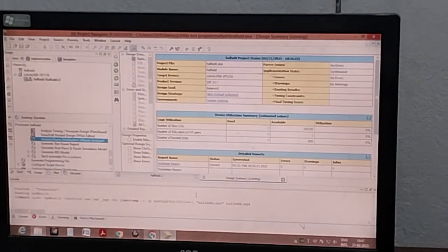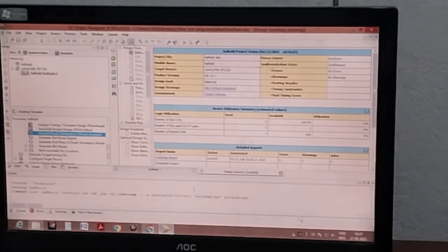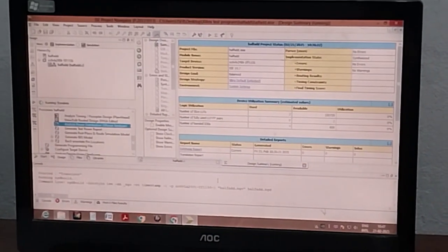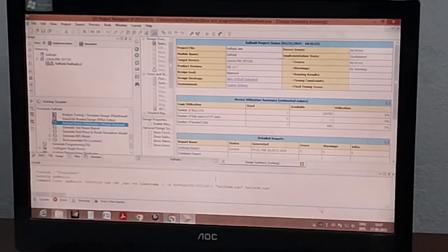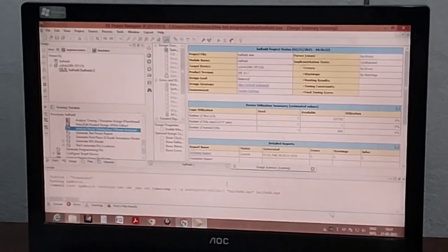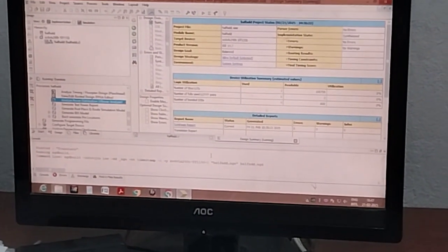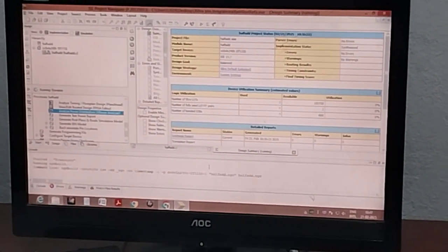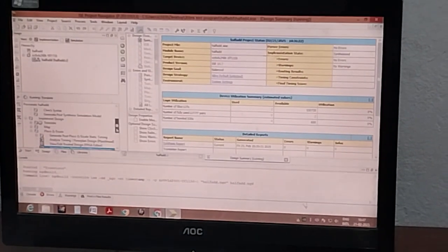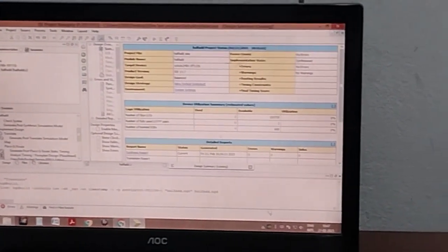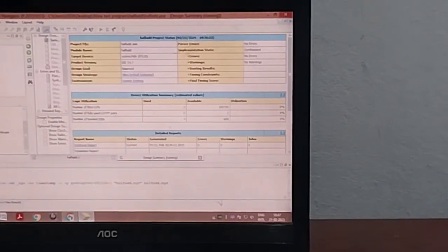There are a lot of procedures, but for simulation purposes we are showing all these things. But whatever Verilog code we are writing for the half adder can be downloaded in the Xilinx hardware available, and from that you can also get the result in hardware. But here we are seeing it in simulation mode. You can check it is coming one by one, translating, then mapping. It will take some time.